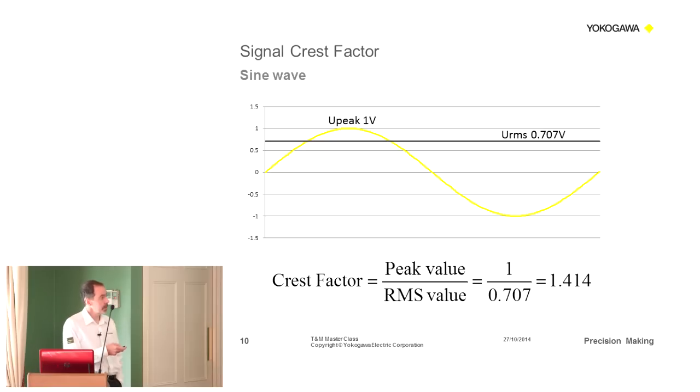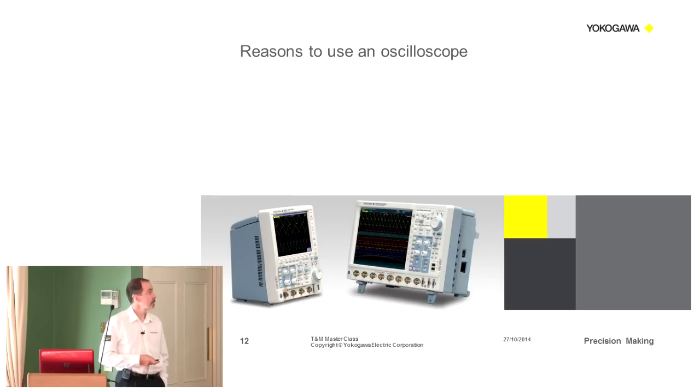So basically, when you've got an oscilloscope type product, which of course is fundamentally defined by peak measurement ranges, if you've got high Crest factors, your actual measuring portion, irrespective of whether you have high resolution or not, can be quite small. So that's where you definitely need as high resolution as you can get. So in practice, you can get Crest factors of 180 or even up to 300 in actual fact.